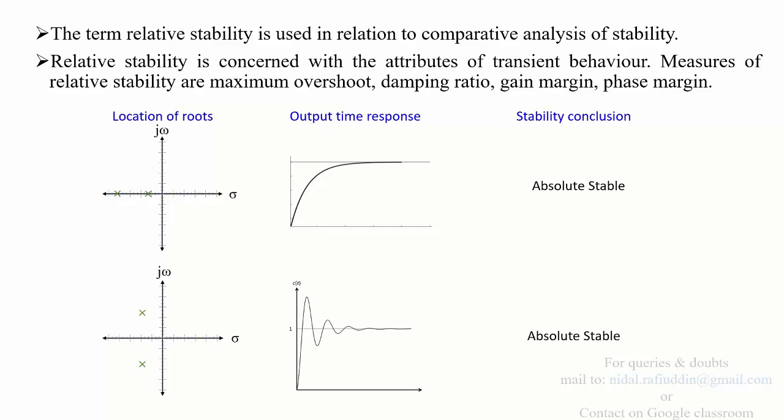Now this is what we concluded in the previous lectures, shown again just to review how we know whether the system is stable or not. For the second order system, we know by looking at the poles located on the S plane. This is the S plane, and since we have two poles located on it, we conclude that we are talking about a second order system. Had there been three poles, it would have been a third order system. Likewise, as many poles as you have on the S plane, the system will have the same order.